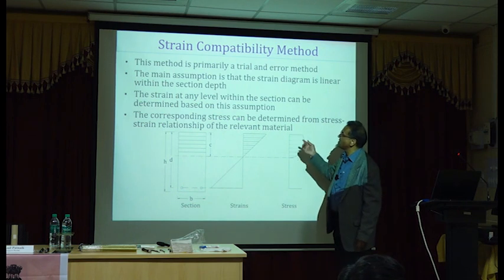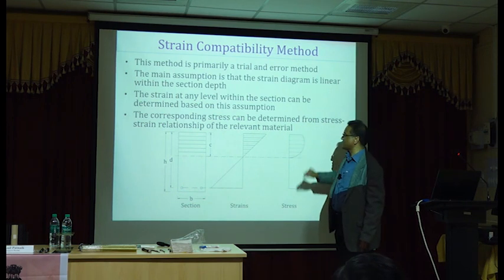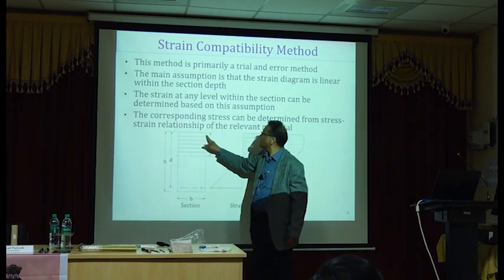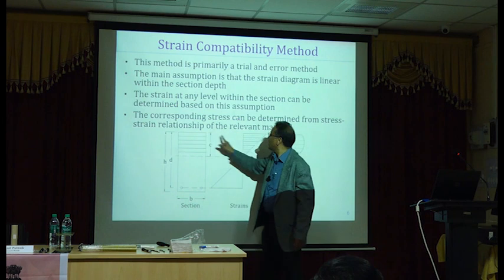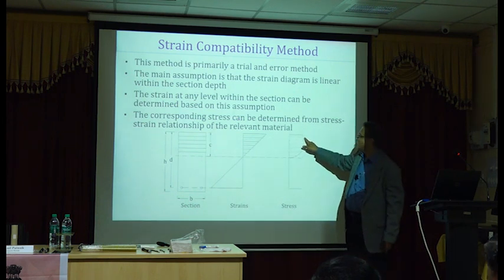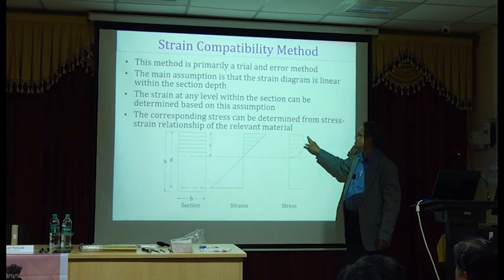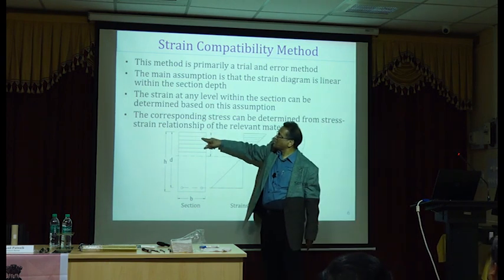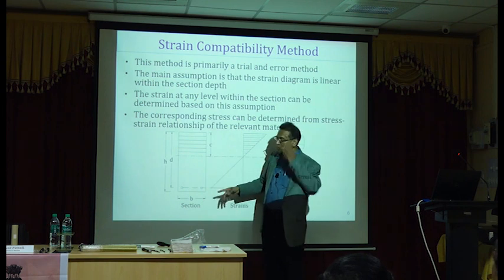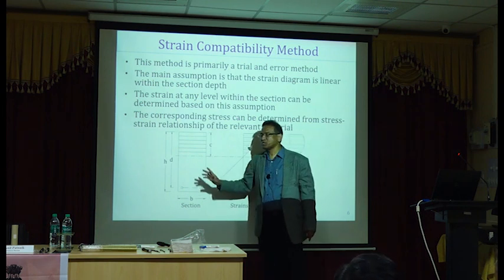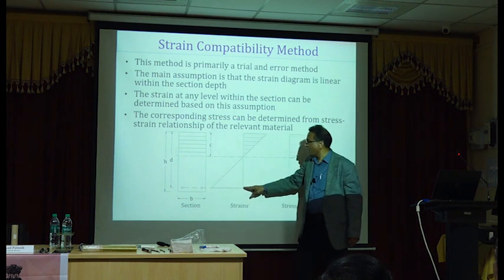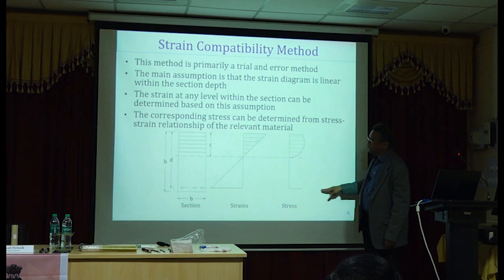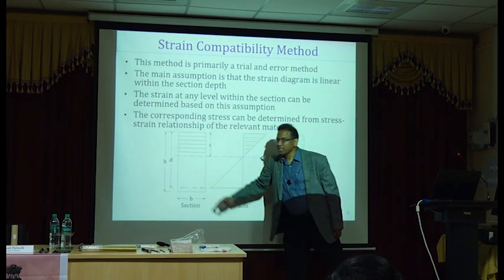The next thing you will do is area times the stress. In case of these layers, the area of this layer is this area here, times the average stress, this stress here. Based on that you get a force. So you'll get 6 forces for these 6 layers, and in this case I am only showing one layer of reinforcement, and this reinforcement will have some strain at this level and the corresponding stress here, and the force is stress times the area of these 2 bars.